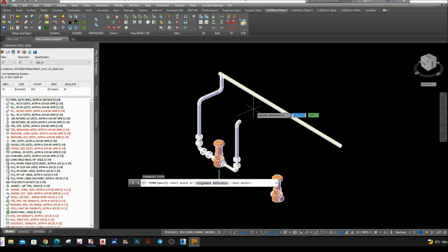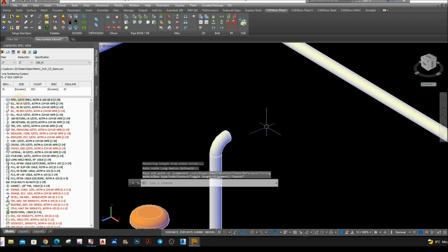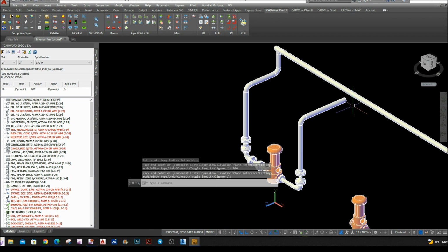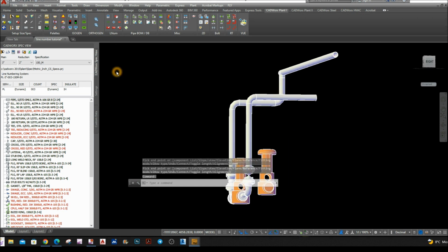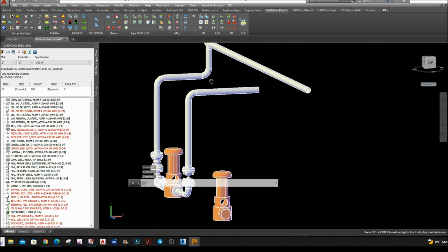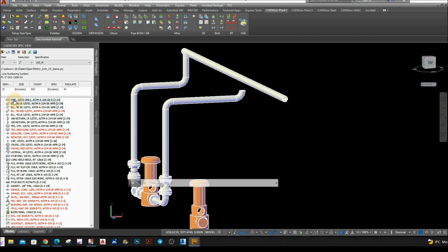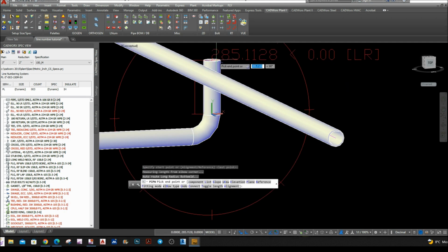And this time I'm gonna add a pipe from in point here, or I can just click this one, click that cross, and enter 1000. Enter again, and I'm gonna check from the right view because I want it to be parallel. See, it has the same height, and then attach an elbow from this in point, bring it upward, attach a nipple from in point and bring it upward and enter 300.